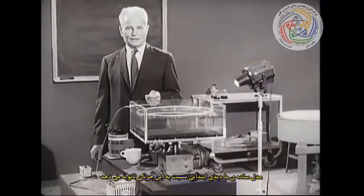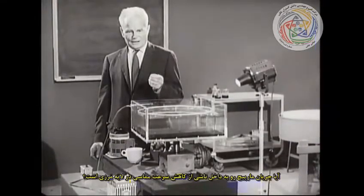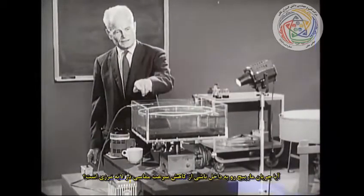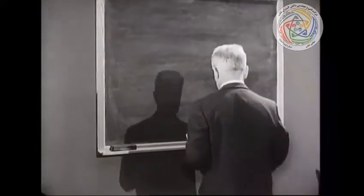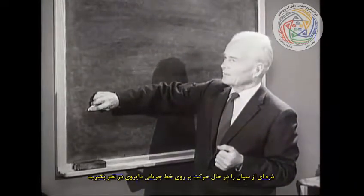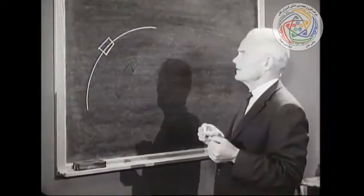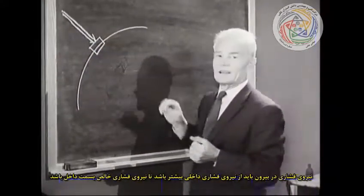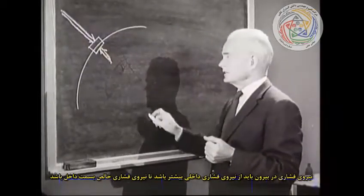Our simplified model has given us some insight into this particular secondary flow. Is it the reduced tangential velocity in the boundary layer which results in the spirally inward flow? Let us consider a fluid particle moving on a circular streamline. The pressure force on the outside must be larger than the pressure force on the inside in order to result in a net pressure force inward.